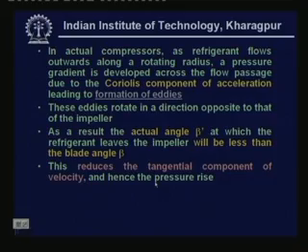So, what is the effect of these eddies? Obviously, these eddies induce some losses, and because of these eddies the actual tangential component at the tip of the impeller is less than the ideal tangential velocity. In fact, the ratio of the actual tangential velocity divided by the ideal tangential velocity is known as slip. Because of this slip, the pressure rise will be reduced.